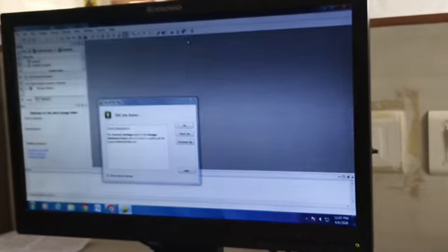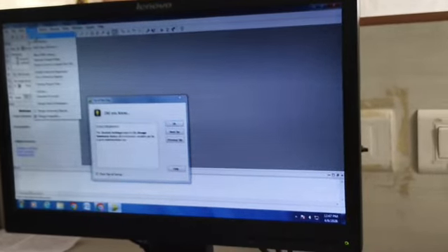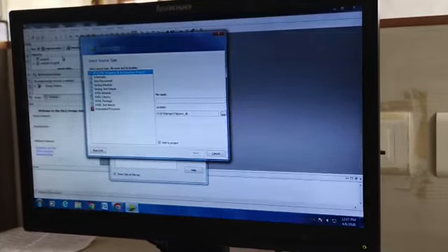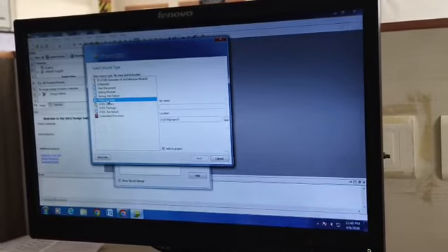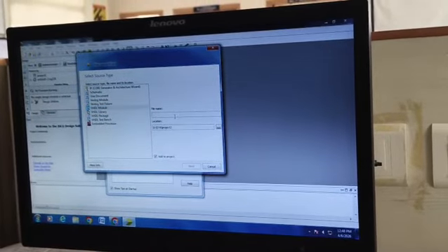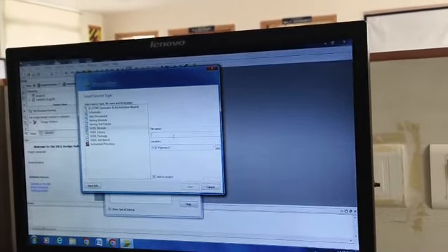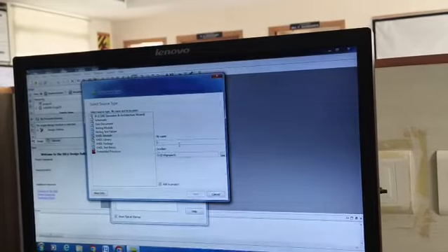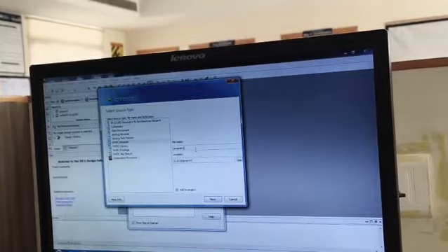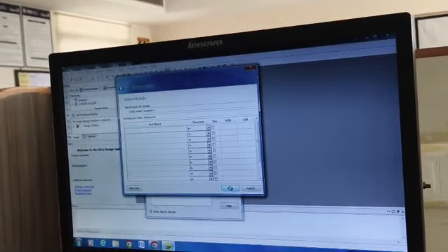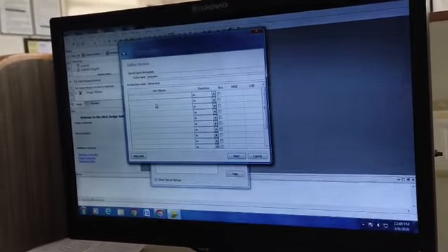Now go to Project and create a new source. Here we have to select VHDL Module and give the file name. This file name should not be the same as the project name given earlier. You can name the file program 1. Then click Next.